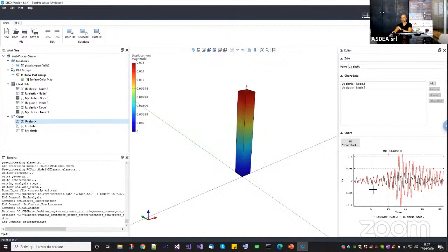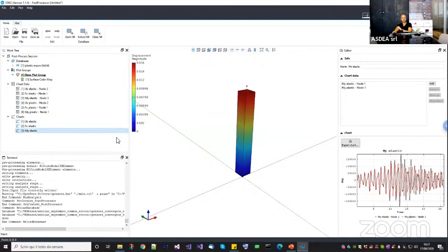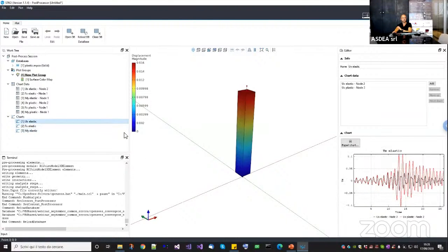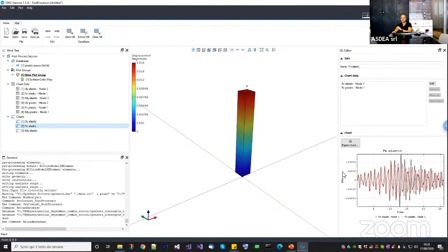Okay, now it makes more sense. As I told you, after a displacement of 10, the elastic forces reached a value comparable to the plasticity at the hinge. And so it makes sense that you see this increased displacement due to the plastic rotation. Then the elastic forces still make sense. They are much smaller than the other one.